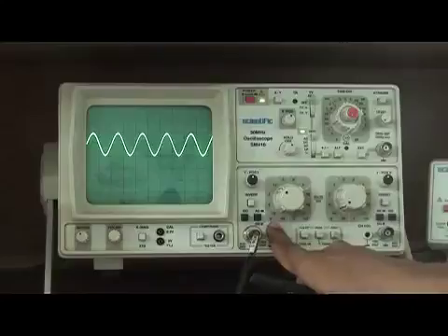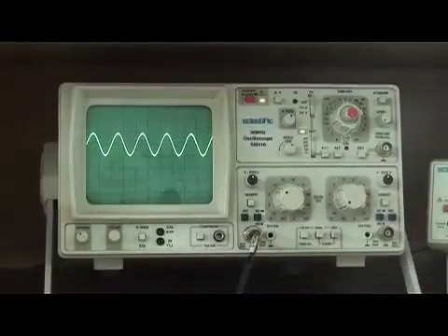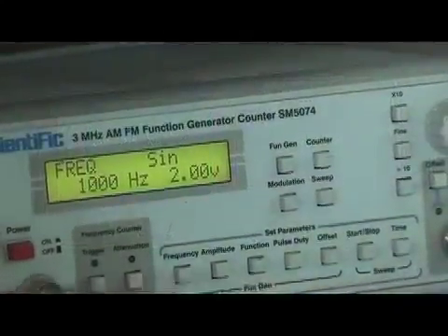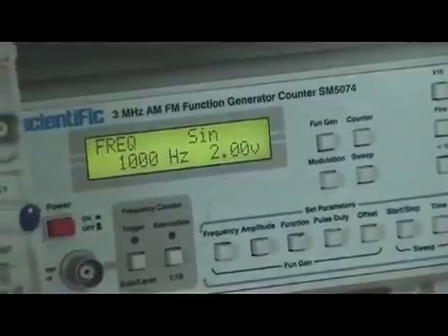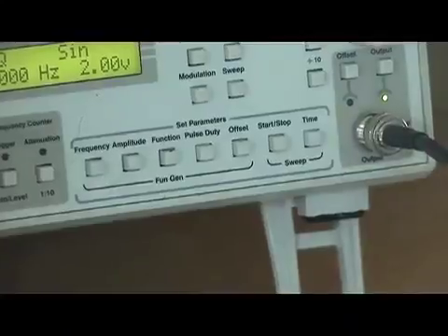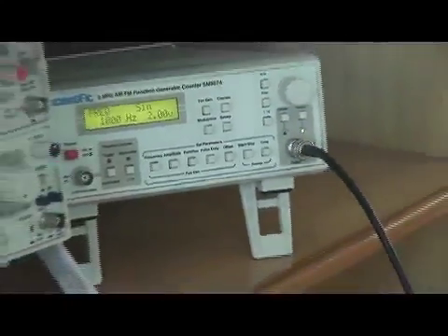So 1.9 volt. We were generating a signal with an amplitude of 2 volt, and now we are getting a signal with an amplitude of 1.9 volts. So what happened to the 0.1 volt? When you transmit this signal from this wire to this CRO, the wire has some resistance, and wherever there is resistance there will be a voltage drop.